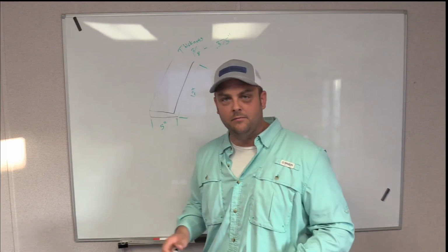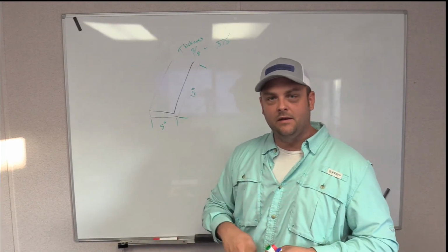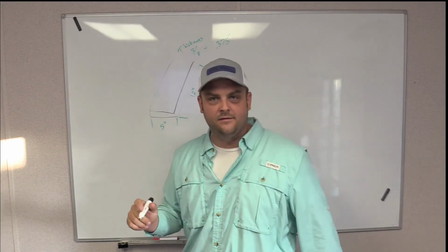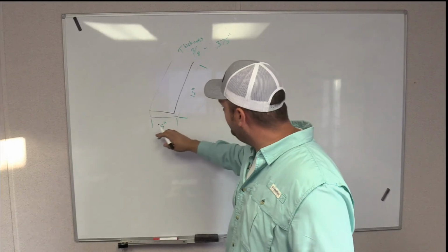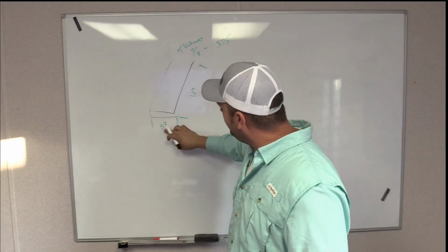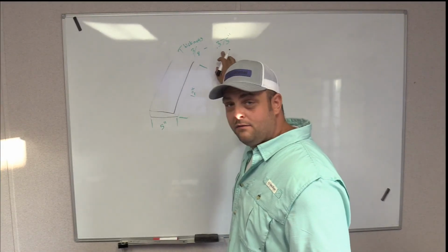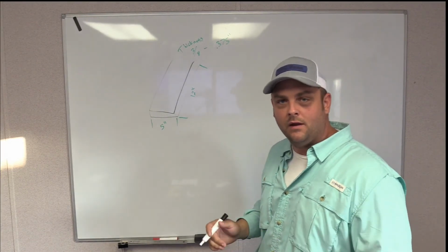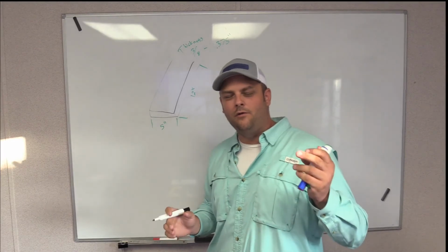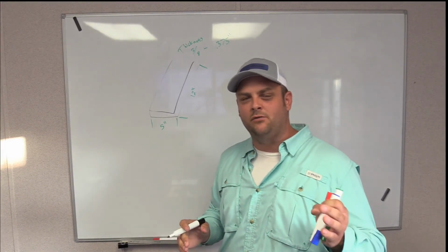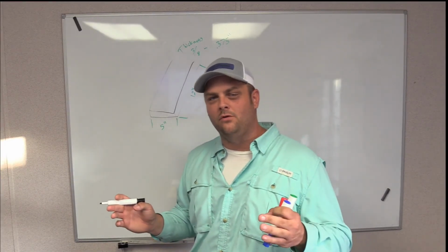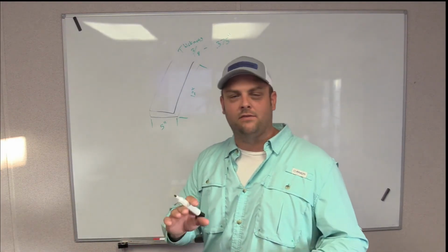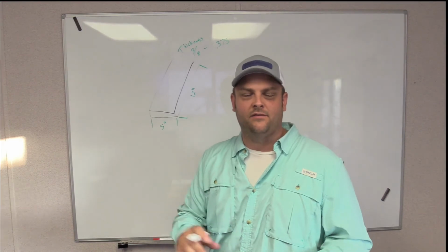If you've never done it before or seen it, it can be difficult, but if you're familiar, it's not that difficult. You take the length times the width times the thickness, multiply that by 0.283. That's the density. The density of steel ranges between 0.280 and 0.290, depending on the density of the steel itself.